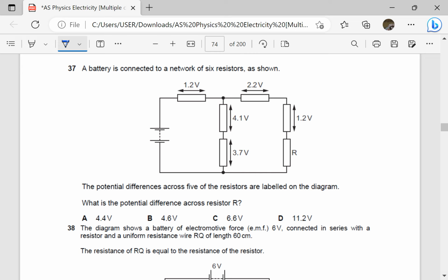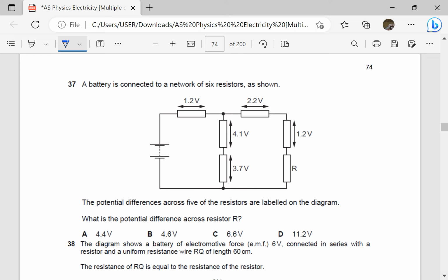So we can use Kirchhoff's second law precisely. We will put a loop here, I'll put a loop there, and I can also put a loop here. So the current, of course, when it comes here, I is divided into, say, I1 and I2. So here we have current I2. If I choose a loop in this direction, for this side, the EMF is,